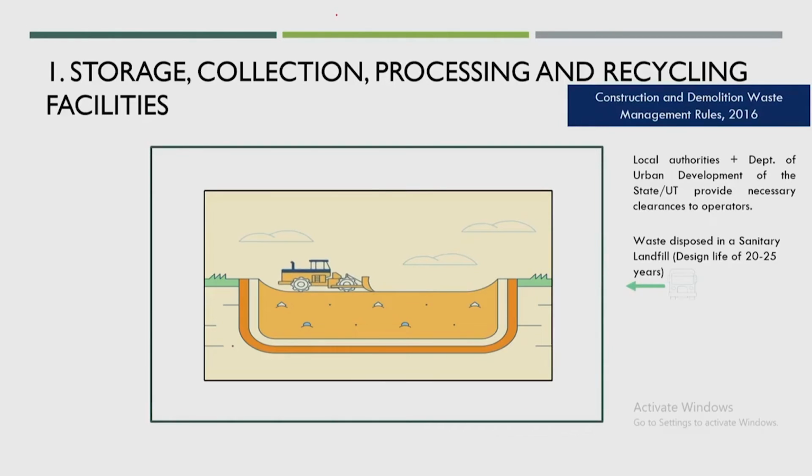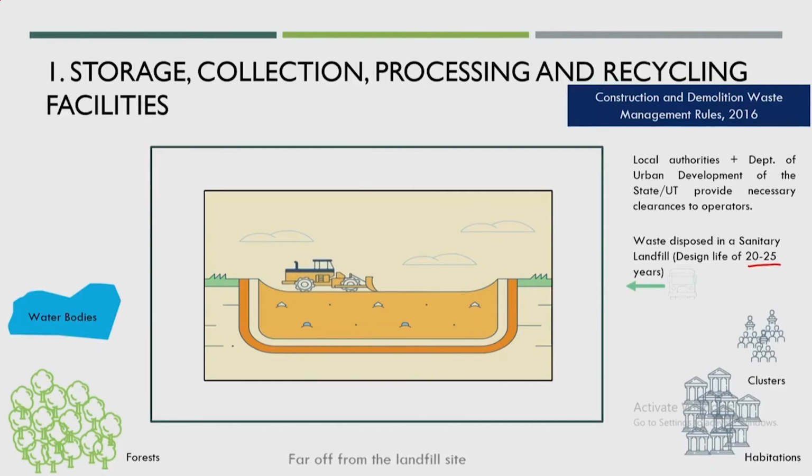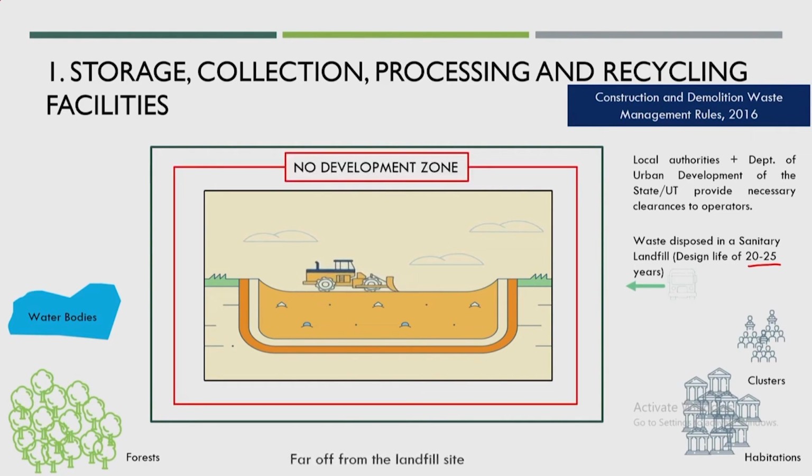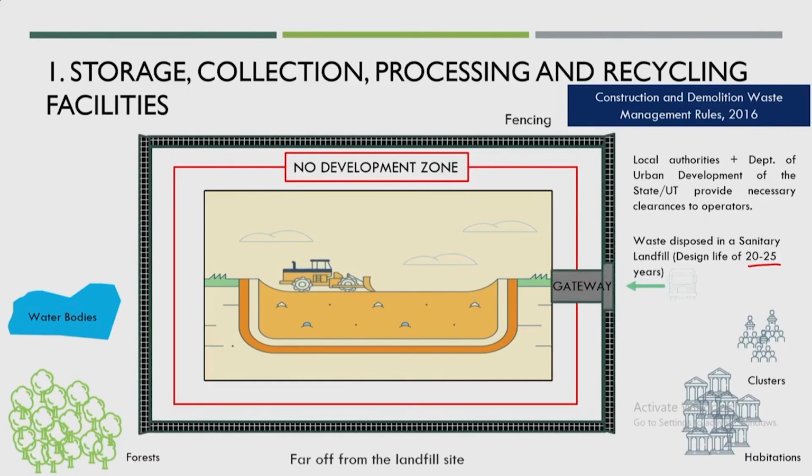This should be designed properly for 20 to 25 years, and located far from the landfill site, far from the forest, far from the water bodies, or far from clusters or habitations. It should not be close to a water body, should not be close to the forest, and should not be close to habitations. And see that in the nearby area there should not be any development. Go for proper fencing, proper approach road,